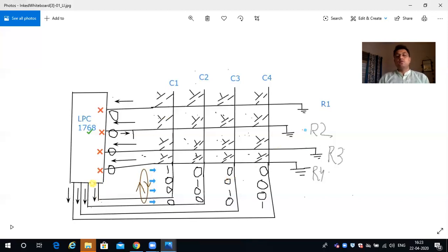Then at that time, what was the state of our column pins? Because that is in our hand. And how is that in our hand? Because we are constantly changing the value. So as and when it was 1, we will notice the value of our pin was this. How can you figure out that value? Using those GPIO registers.